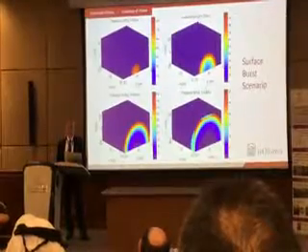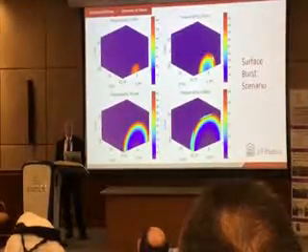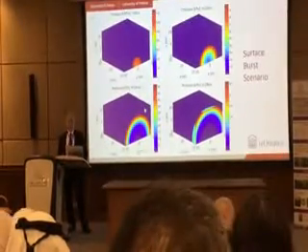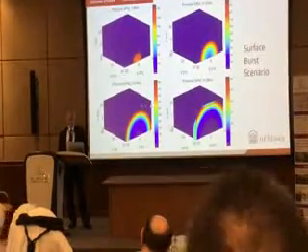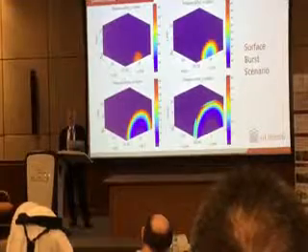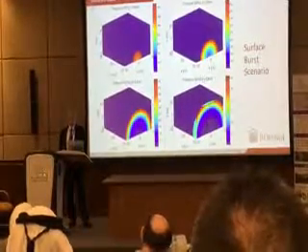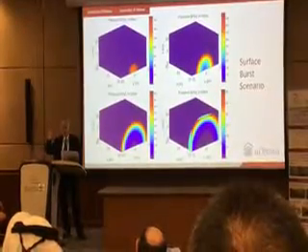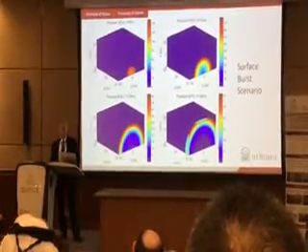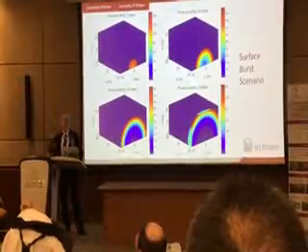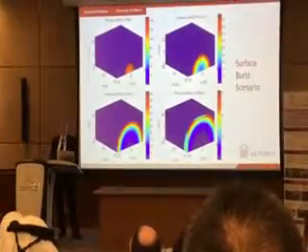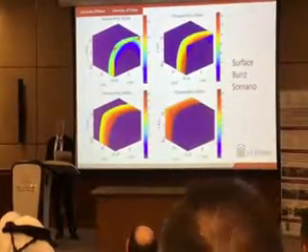And then at 10 milliseconds, it starts increasing, and at 14 milliseconds, almost 2/3 of the front wall is covered. And then at 18 milliseconds, the entire front face is covered, and this is the full reflected pressure. Then what happens is that the pressure clears away, it starts escaping from the sides and from the roof. This is called clearing time.